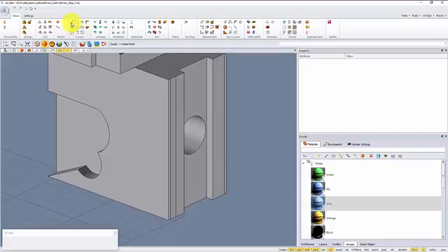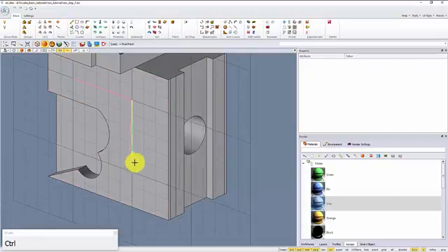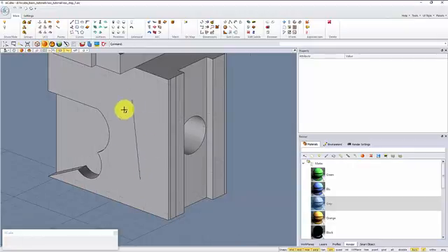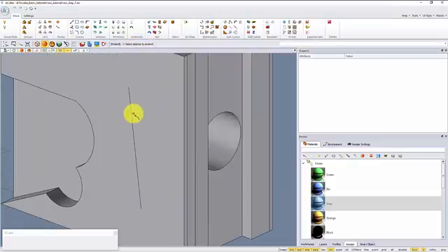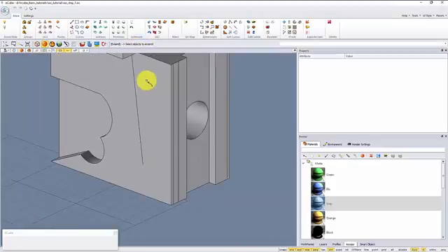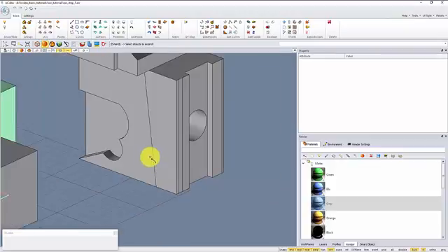If we draw a curve on a surface using the Control key, the curve does not belong to the surface, but we would like to extend it to edges, we can use the extend tool. Select the boundary object. I'll select the solid, select the curve to extend, this one here and that one.